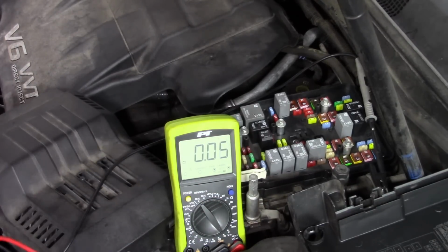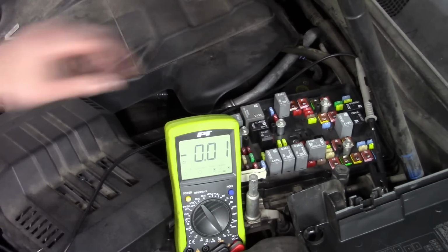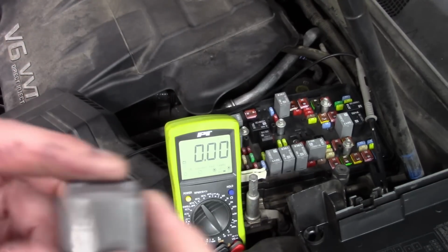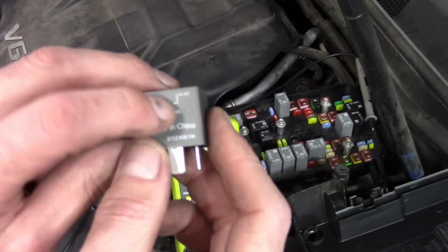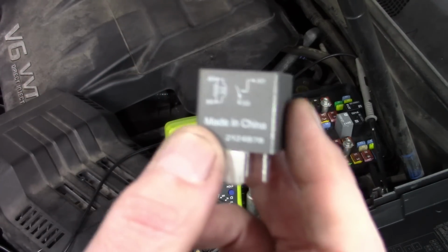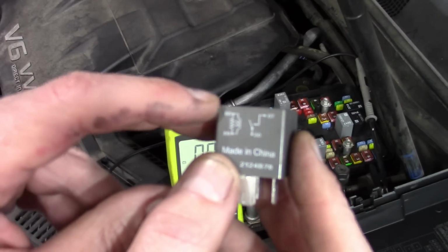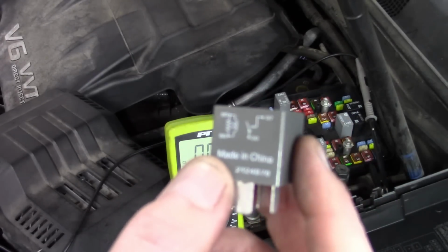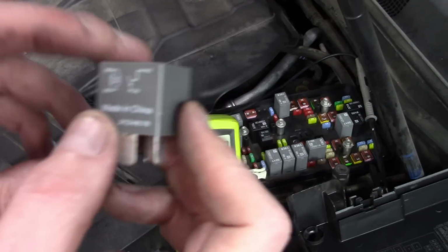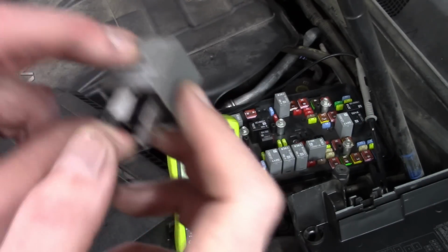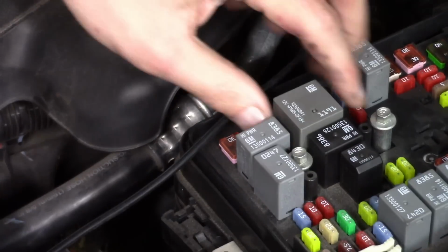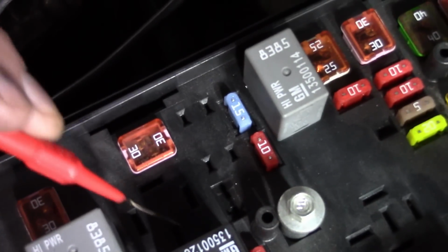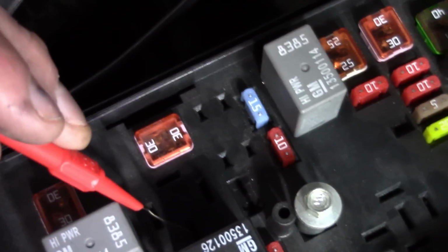Now, as I mentioned earlier, a lot of times, not always, but a lot of times, your relay will be set up so that on your load side, one of your load sides will have power at all times, whereas on your control, you will only have power that comes on with the key on or the engine running. So maybe this car is like that, we'll see. We know we've got 87 and 30 here. So if I line my relay up into the port, that means 87 and 30 are these top and bottom ports.